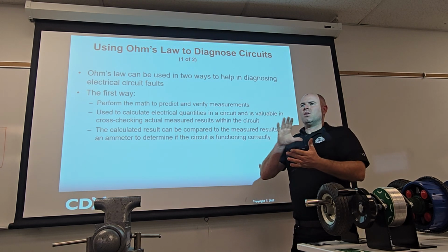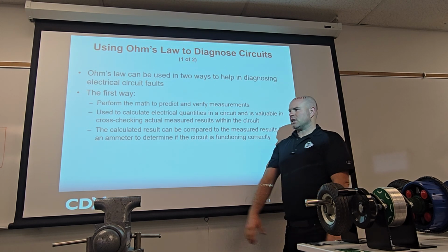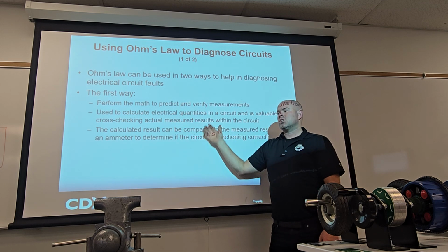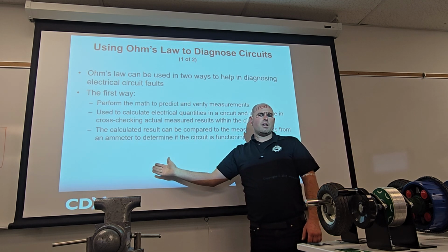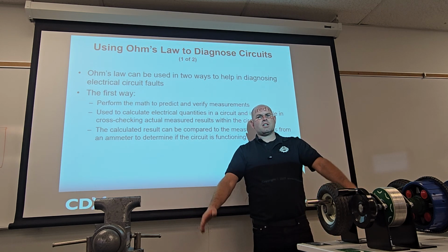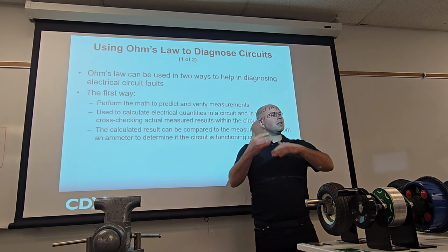Make sense? So when you pull up the service manual, it's not like check this connector for 12 volts, check this connector for 11.9, check this connector for 0.1. Make sense? It's more like, here's the diagram. Check anything you need to check, but you need to predict it yourself, right?